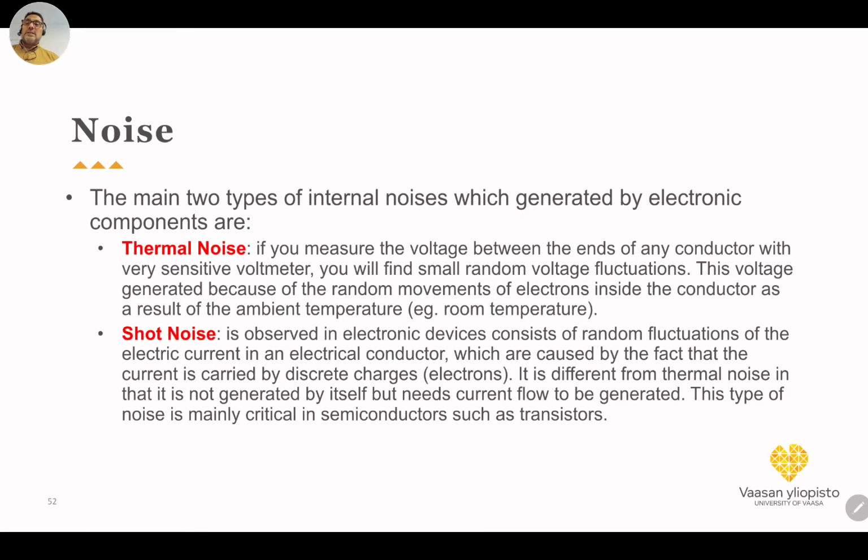If the signal is considerably less than the noise, then of course the receiver will not be able to detect that signal, because it is under the noise floor. Which noise? Noise which is generated inside the receiver itself. This is one reason why the front end amplifier should be designed very carefully to have very low noise properties, or low noise figure.